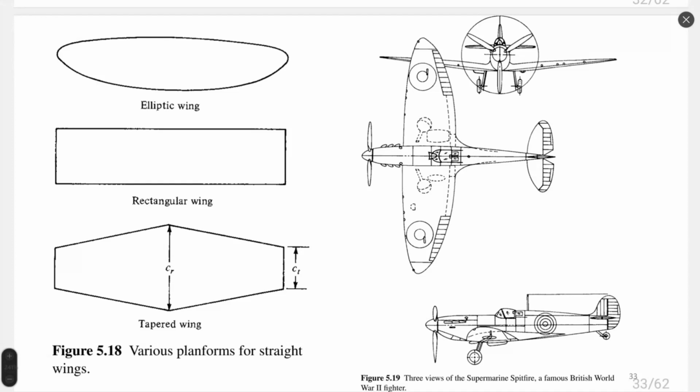Aerodynamics has a long, more than 100 years old history. And the tapered wing, something that you already saw in the previous formulas, right? Tapered wing is extremely interesting because it allows to have a reduced value of induced drag. It's simple from a manufacturing point of view, just a linear shape, right? Having some increased performance with respect to a rectangular wing.